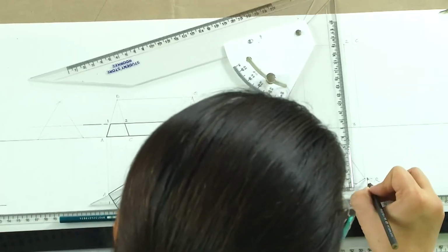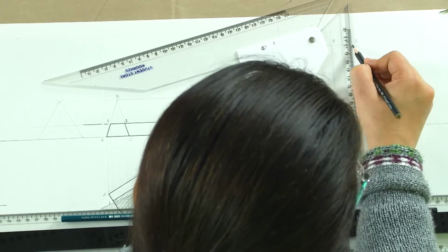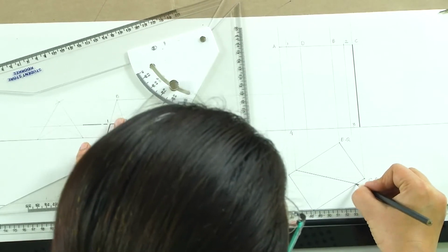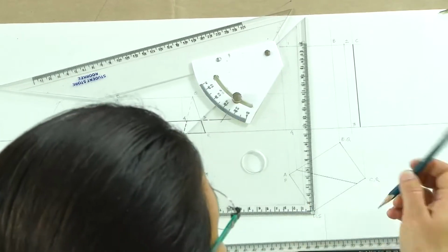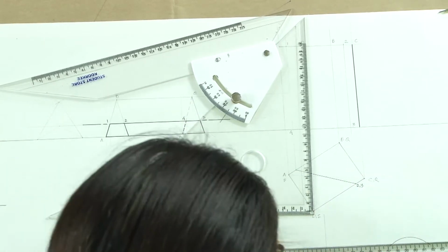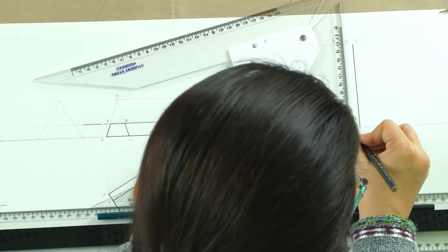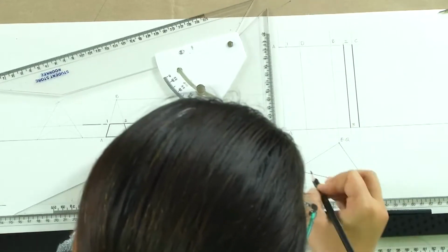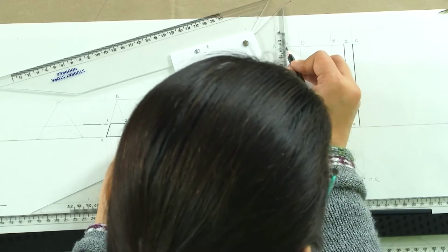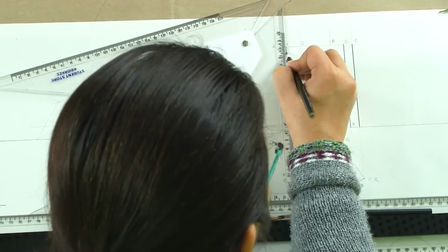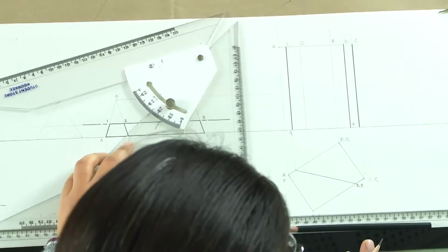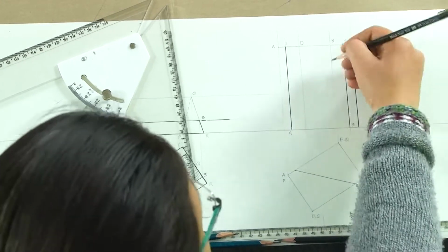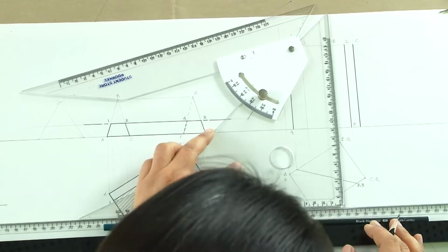I will darken it directly. So, we still have CR in place. So, that is going to remain intact. It is not getting cut. It is still there. We have another edge here which is 2, 3. So, I will label it here, 2, 3, which we will see in the front view. Then we have this 1 and 4 which we see here. One and 4, and this D is not there, and this edge BQ is at the back. So, it will be actually seen as a hidden line.